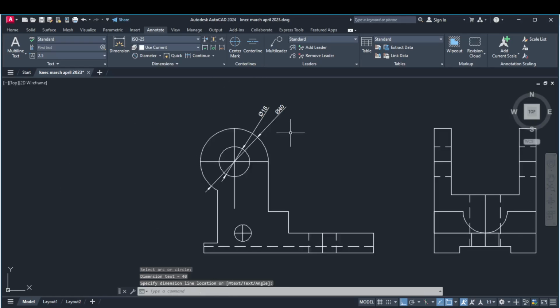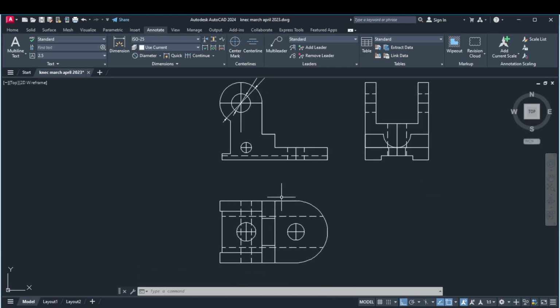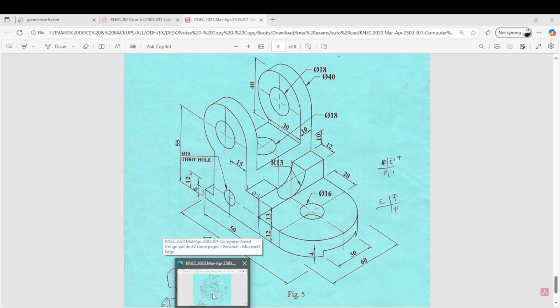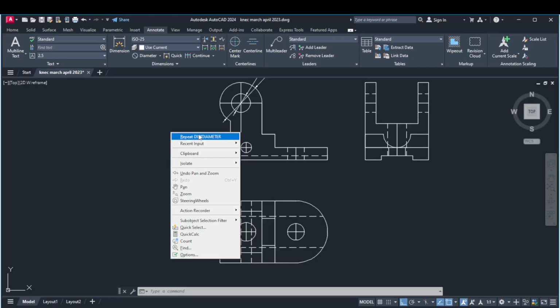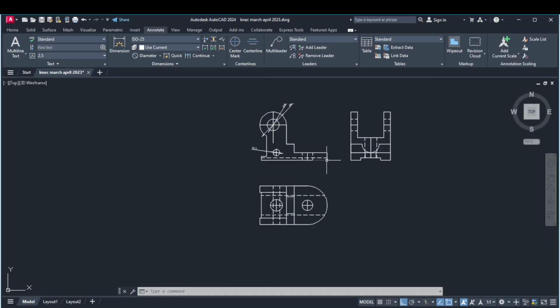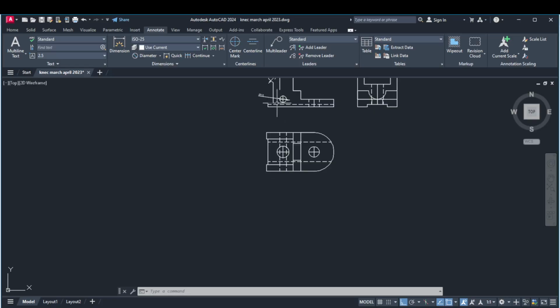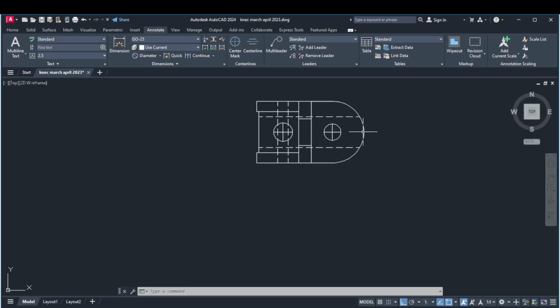So we'll have done that, and then what about this circle? Let's confirm how they dimensioned it. That circle is also in diameter, so we again pick diameter, repeat the dimensioning, then place it here. Then the distance between this section and this section is the same distance as from this section to the outward section here.